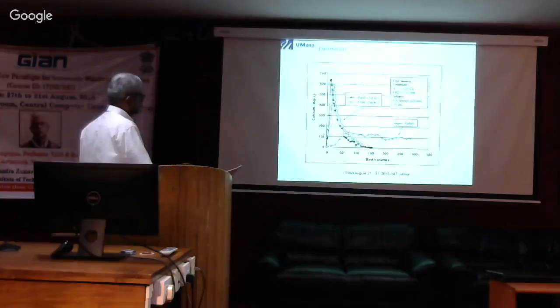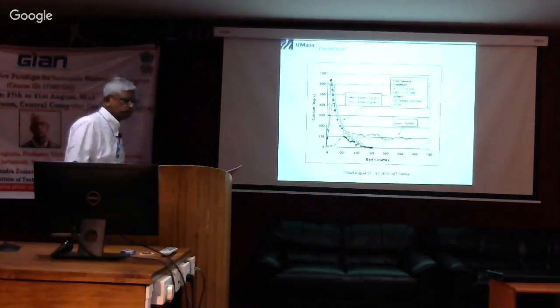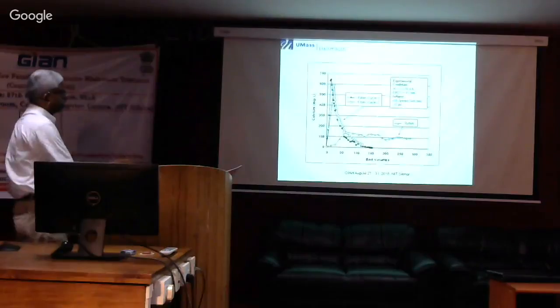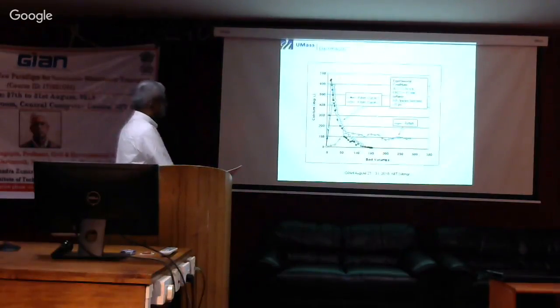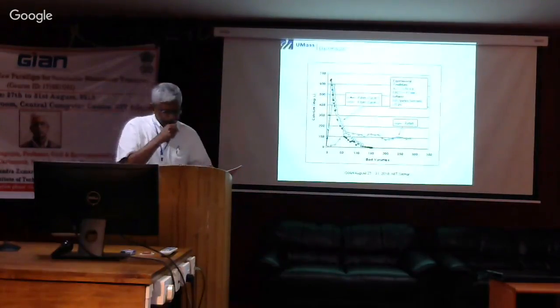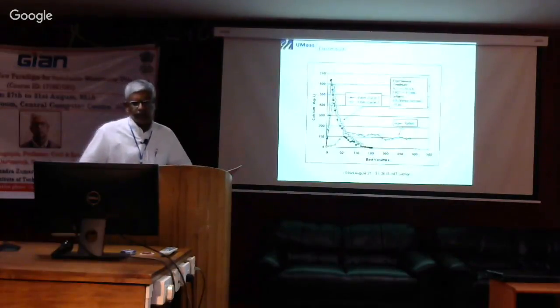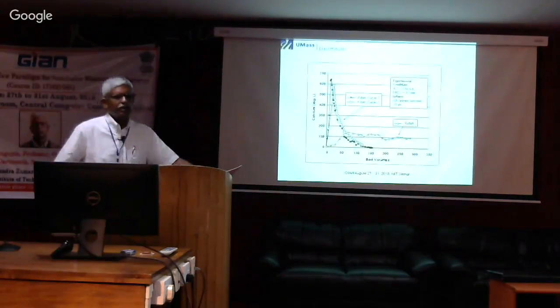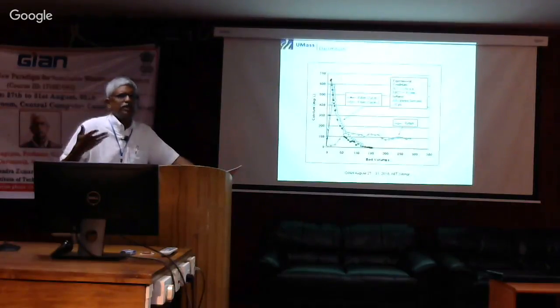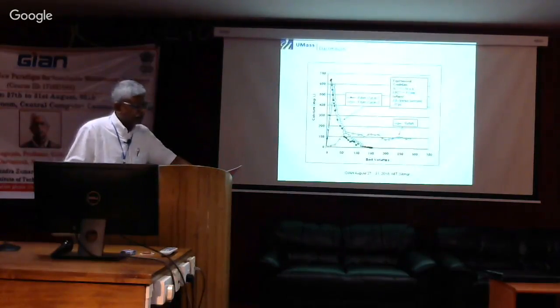Whereas the fiber, as you can see, this one, which is cycle 1, much better regeneration. Within 125 bed volumes, we were able to get out more than 95% of the calcium. Now, whenever we present this result, people say 125 bed volumes is very high. And the answer is yes, it is high, but keep in mind this is carbon dioxide, this is flue gas, it is the waste material.